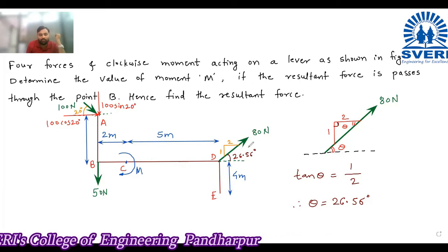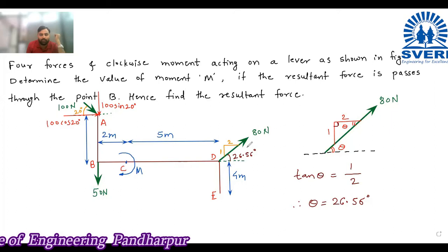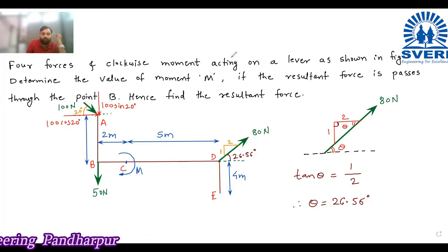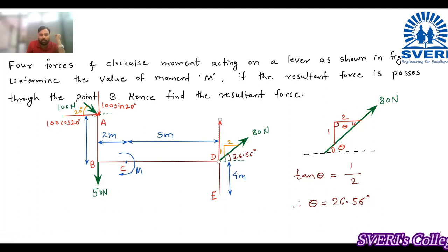Now here also, if you see, this is the force of 80 Newton. Again we need to resolve this force. So draw one line parallel to the y-axis, and one line parallel to the x-axis.